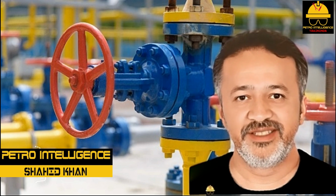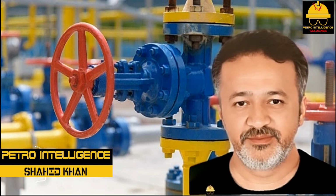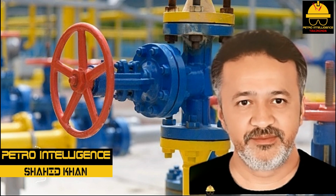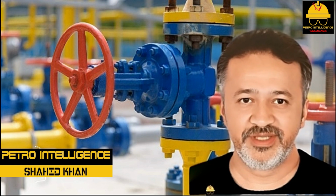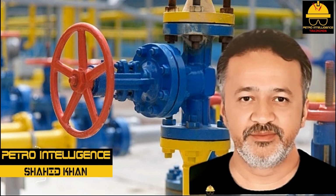A gate valve places a movable metal gate in the path of a process flow in a pipeline. Gate valves are considered excellent devices for process services that are used infrequently. A globe valve places a movable metal disc in the path of a process flow. This type of valve is the most common one used for throttling service.